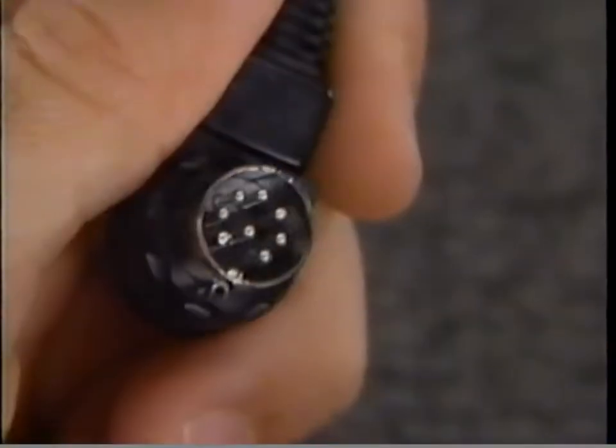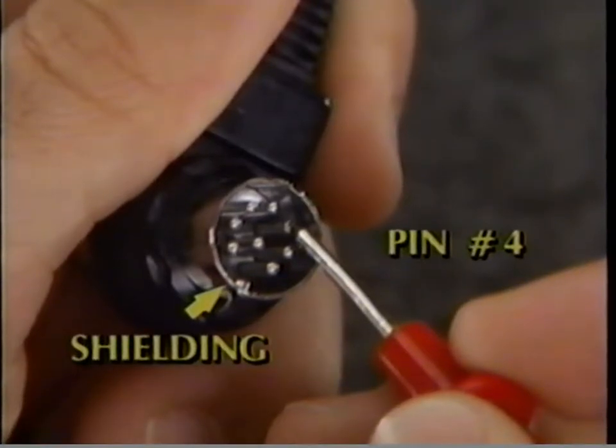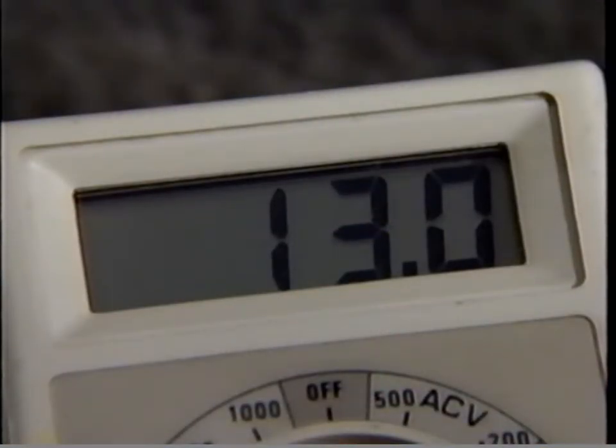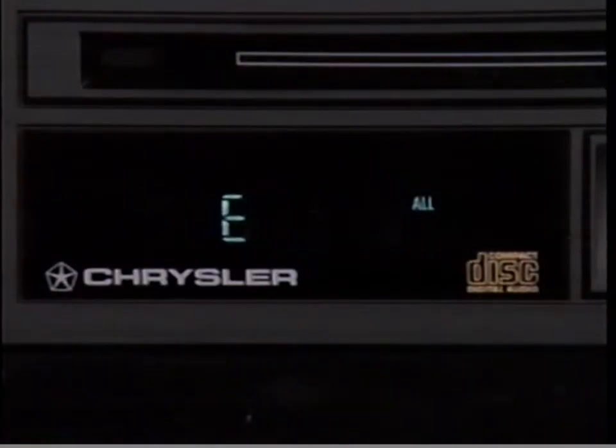Next, with the radio on, we'll check for voltage at pin 4 and shielding of the CD cable. If there is ignition voltage at pin 4 and a good ground, then the problem is in the player and it must be replaced. I've loaded discs into players and they've been ejected immediately, and the player displayed an E.